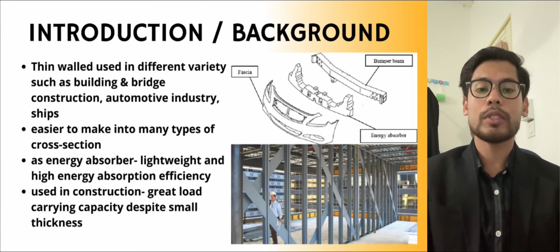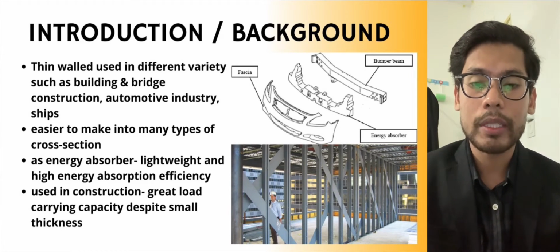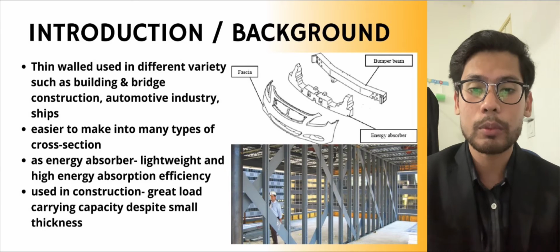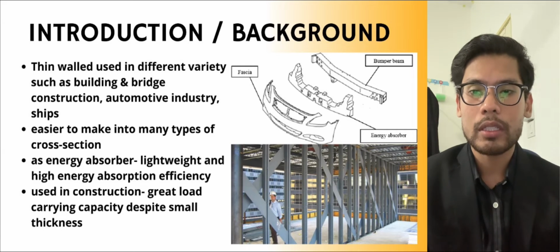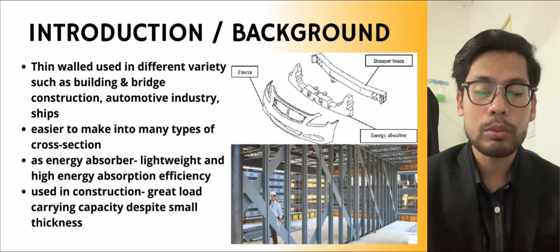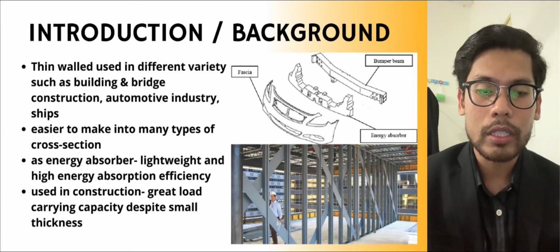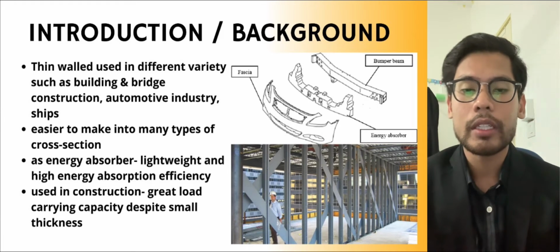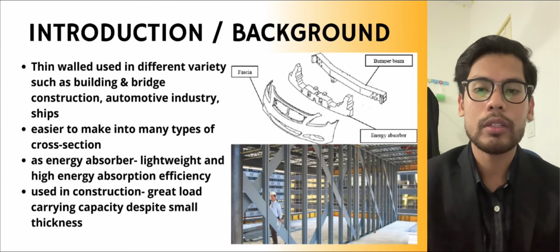In China, rock explosion incidents in coal mines have become a common occurrence in recent years and have become the biggest mining disaster. The hydraulic safety valve is too late to operate for pressure release protection because the surrounding pressure increases rapidly due to rock burst. This will result in complete system failure, instability and destruction, as well as equipment damage and casualties. The development of a hydraulic column with better energy absorption ability and fast dynamic yielding is needed to improve the anti-impact ability of roadway hydraulic support equipment.